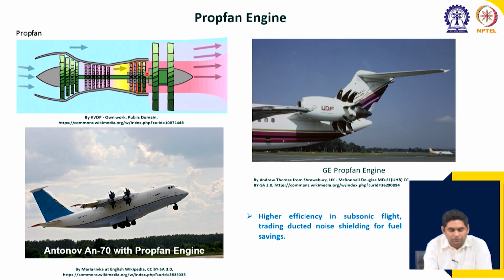These turboprops are generally designed, as we have discussed, to fly at moderate or low speeds, low Mach number such as Mach 0.5 or around that. The issue with turboprops was that, the way these are designed, if you go to very high speed, the edges of the blades will go to transonic or supersonic conditions, which causes issues with the airflow process.